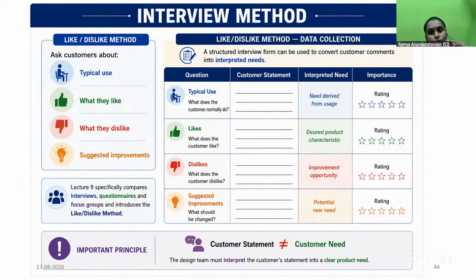A structured interview form can be used to convert customer comments into interpreted needs. In an interview, you can meet one on one and fill it in, or sometimes you can ask them to fill it in. This will give you a better idea so that you can understand their need. A customer statement is not a customer need. The design team must interpret what they are trying to say. Sometimes they may not be able to state it properly, but you need to interpret it and clearly understand the need of the customer. A statement is different from a need. Okay, so that is very important.